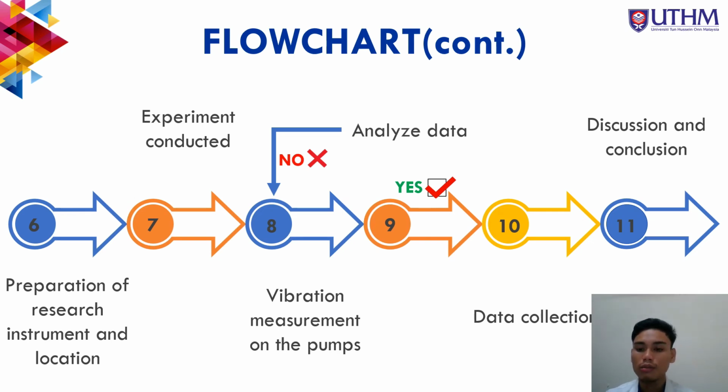When the measurement is recorded, we analyze the data. If the data is not clear or has a defect, we will record the vibration measurement again. If the data is acceptable and can be used, we go to the next stage, which is data collection.